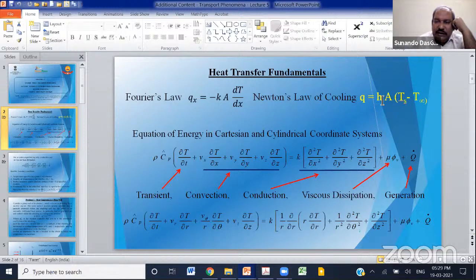If the flow is through a pipe, that D could be the diameter. If the flow is over a flat plate, that length scale could be the actual length over the flat surface, and k is the thermal conductivity of the fluid.